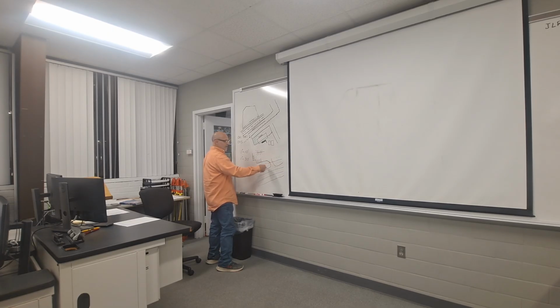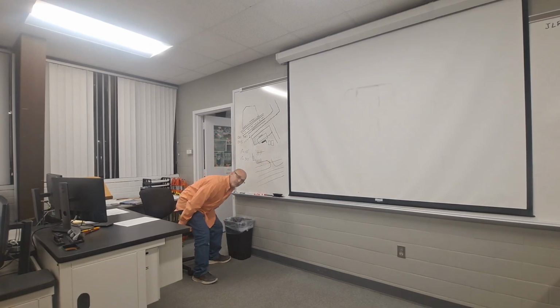So you're gonna break that shoulder line right there, bring one or however many entrances you have to your parking lot. You bring them across, you're gonna have a 15-foot radius arc right there, a 15-foot radius arc on that side also if you're turning both ways.